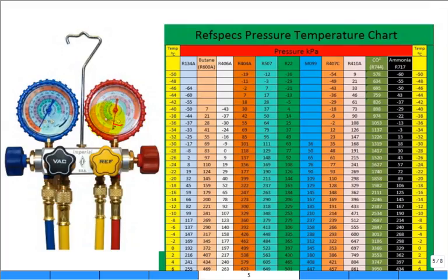Anyway, there's a lot of these. And this gauge over here really is telling you the pressure temperature data, like on that chart. They'll even call it a pressure temperature chart. The old refrigerant guys would have a little card in their pocket, and they'd pull it out and look and say, okay, what refrigerant am I using today? Oh, it's 134A. And they'd say, what is the temperature right here? Maybe they come down here, and they say, at -8, I expect the saturation pressure to be 117 kilopascal. This is the pressures in kilopascal, and the temperatures in degrees C.